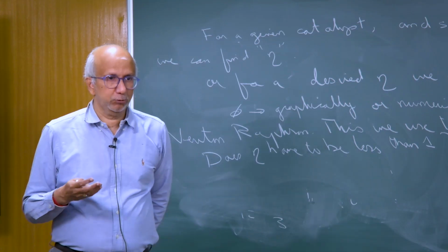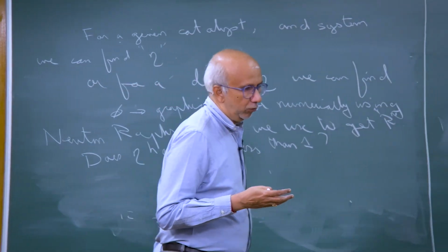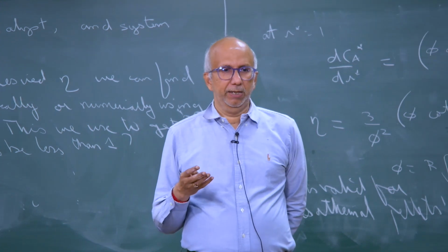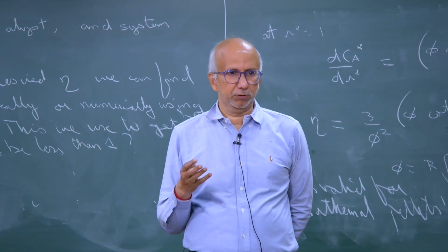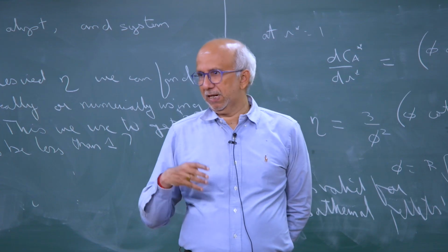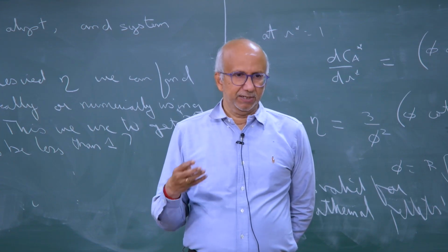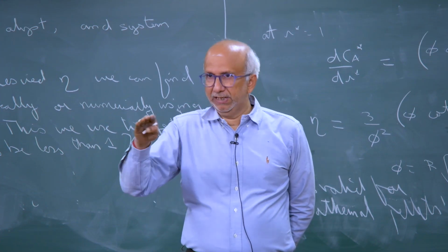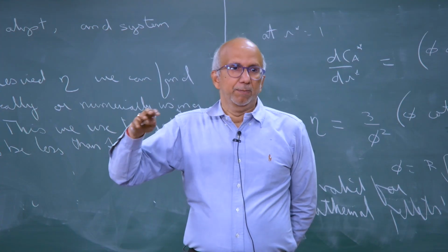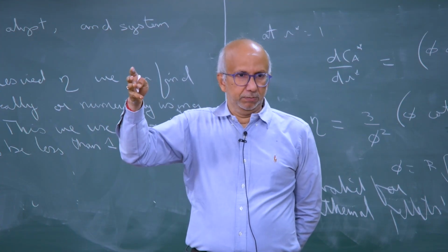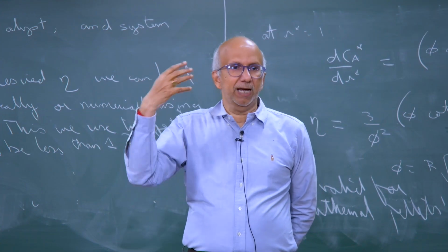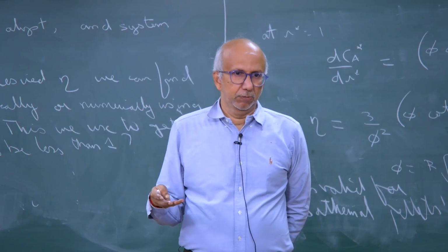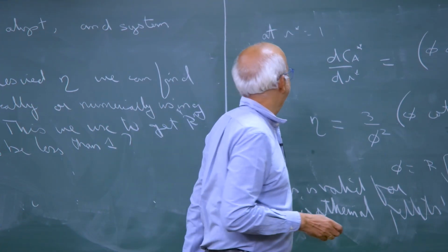Okay. So, eta is going to be less than 1 for typical nth order reactions if it is isothermal, but if it is non-isothermal like an exothermic reaction, temperature in the pellet can be more than the surface. So, reaction rate can be high because of the temperature. Here concentration is decreasing, so reaction rate is low at the center, but temperature can be high if it is exothermic. So, you can get a higher reaction rate in the numerator, and you can get a higher effectiveness factor, more than 1. Okay. So, basically keep that in mind.